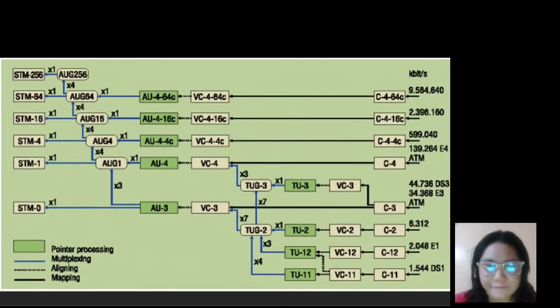So here is an example diagram of how SDH can work. SDH combines n signals with a bit rate of b to form data streams with bit rates of n times b on a synchronously clocked network. The individual transmission paths have minimal clock discrepancies.